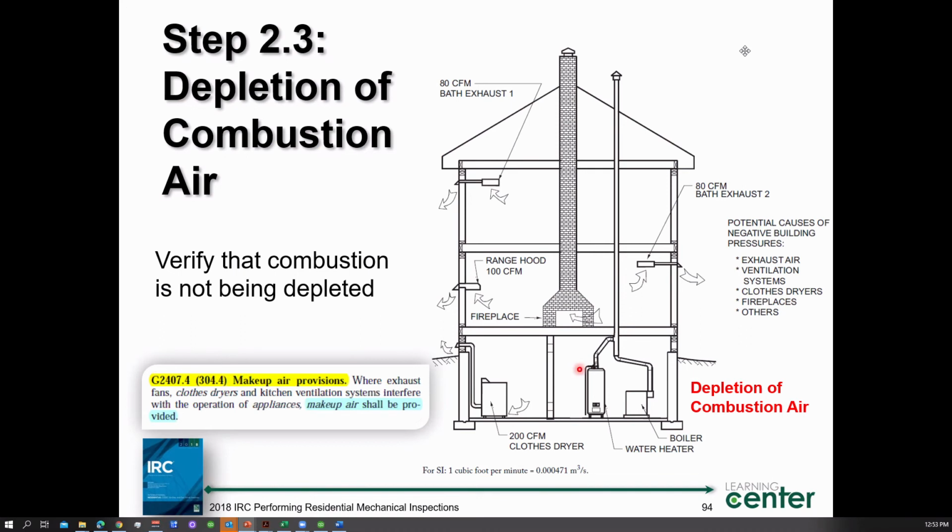It's called incomplete combustion. Complete combustion, the byproducts of burning natural gas, remember, are water vapor and carbon dioxide. Incomplete combustion, where I have my flames licking out, incomplete combustion, bad fuel to air ratio, leaking out of the draft hood. Now we're introducing carbon monoxide, ladies and gentlemen, into the space. Combustion air is missing here. You see what happens here?